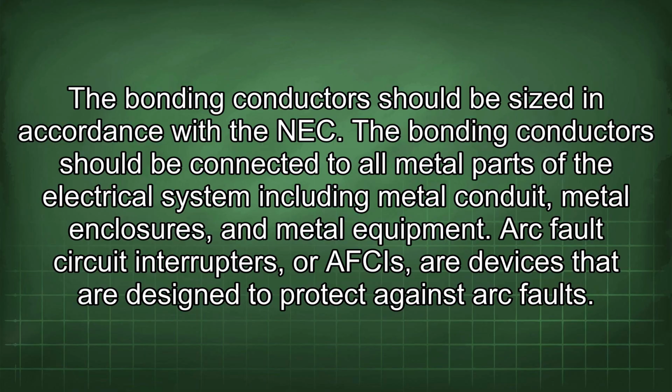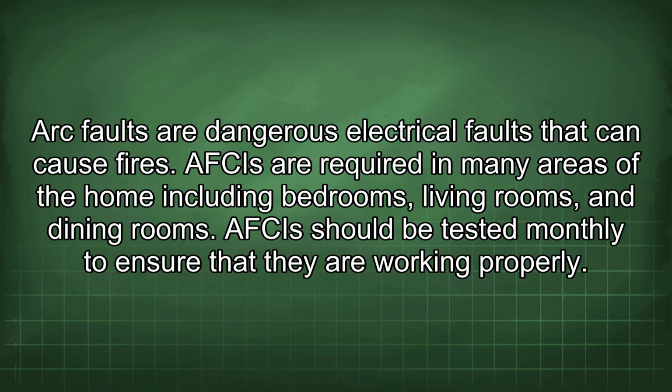Arc fault circuit interrupters, or AFCIs, are devices that are designed to protect against arc faults. Arc faults are dangerous electrical faults that can cause fires. AFCIs are required in many areas of the home, including bedrooms, living rooms, and dining rooms. AFCIs should be tested monthly to ensure that they are working properly.